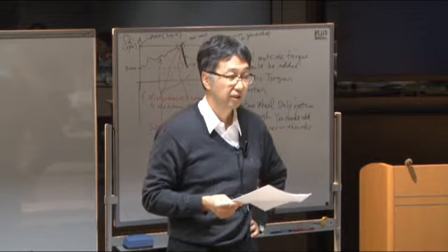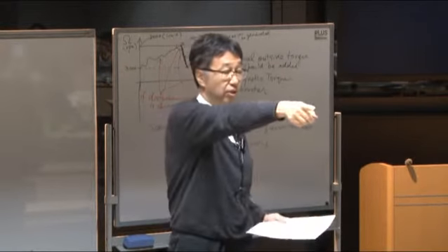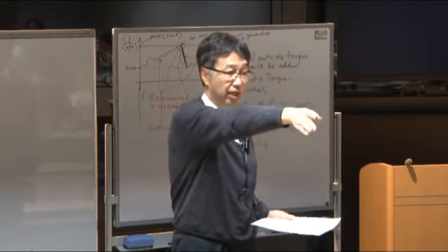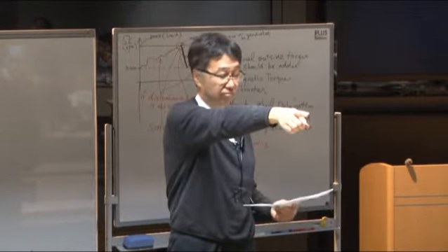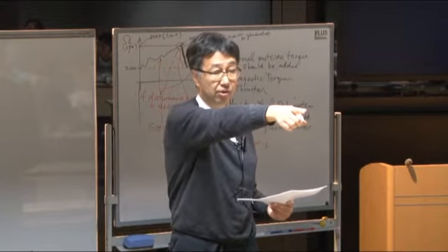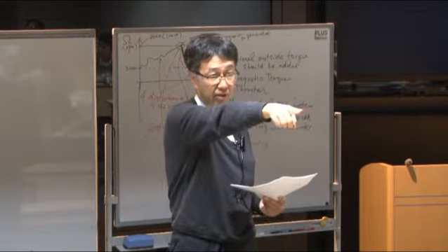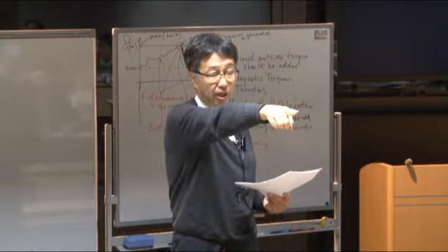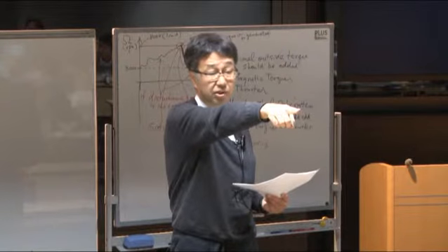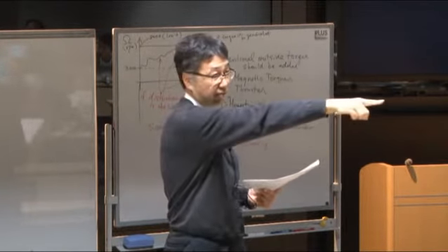Okay. So I'm the communication satellite, and you are the ground system. So you are the target. And if I have an error in the roll and pitch axis, what happens? So this is the antenna boresight, the antenna direction. If we have a pitch axis error, then the antenna direction moves like this.